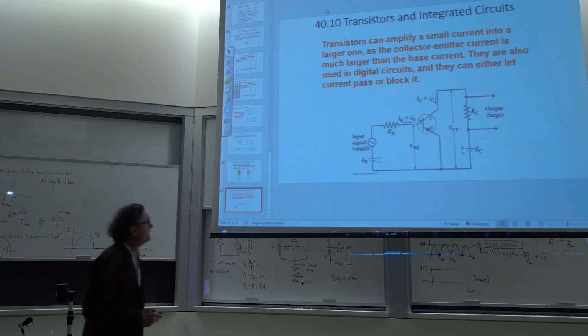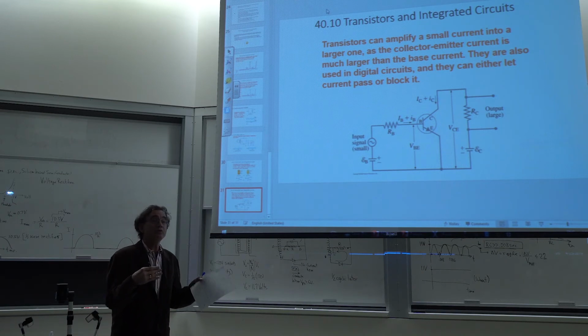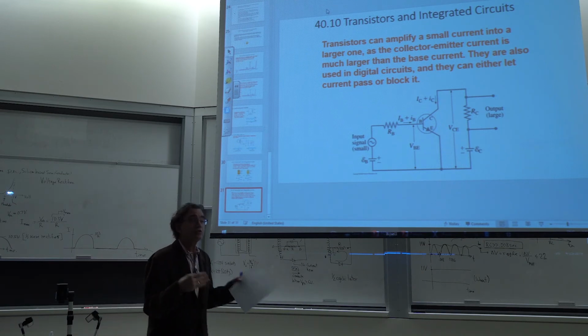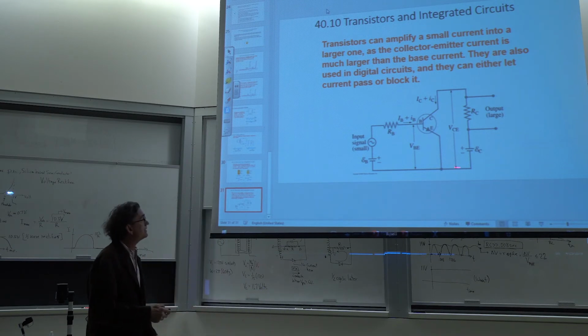For simplicity, remember we said we're at freedom to choose any point to be ground in the circuit. That's our 0 voltage reference, right? I'm going to choose this line of the conductor right here to be my zero voltage point. Everything relative to here is zero volts. Everybody got that? I'm going to tie this line right here on the circuit to ground.